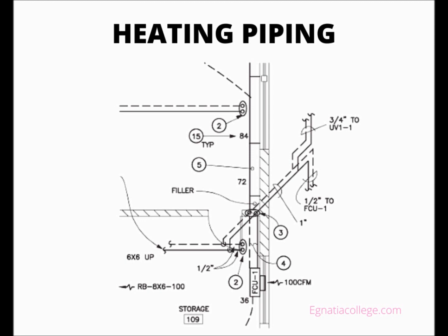Sheet H1 of the School Edition drawings combines plan views and isometric schematics. The long runs of pipes are shown in plan view to indicate where the pipes are in relation to the walls. Where the pipes need to drop down from the ceiling to the level of the ventilators, they are shown in isometric views. For the sake of explanation, the following discussion traces the hot water supply piping, broken line, in room 109, the storage room on the first floor, E7 on sheet H1.